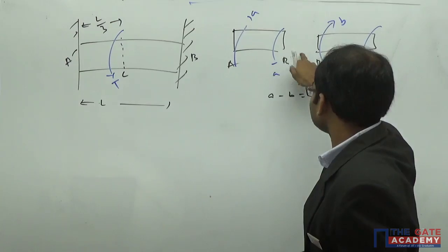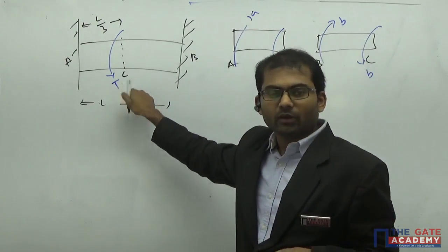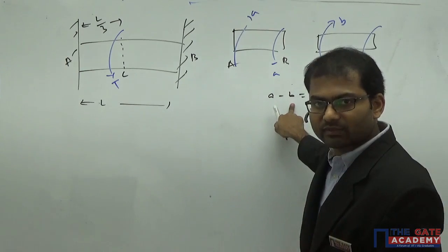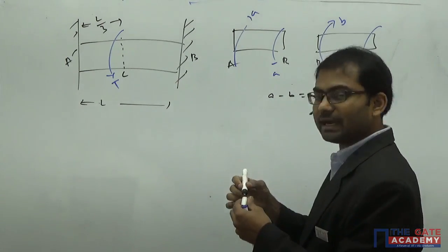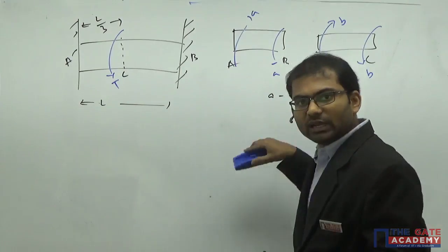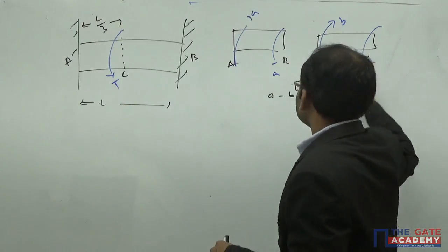So you have only one equation from static equilibrium here. Understand? That means net torque is equal to the value T here. Okay, so only one equation, two unknowns. So you can't get the answer very easily here. Understand? So this is a statically indeterminate case here. To solve this one, we'll go another way. We don't follow this method here.